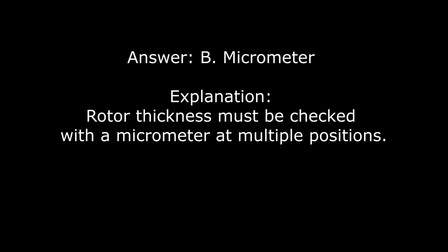Rotor thickness must be checked with a micrometer at multiple positions.